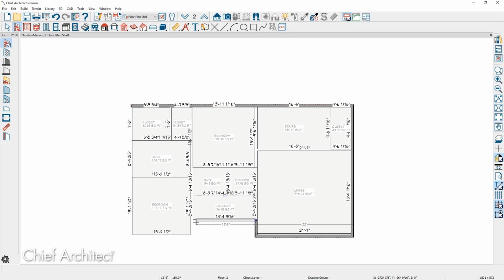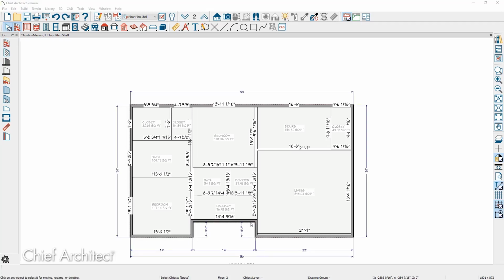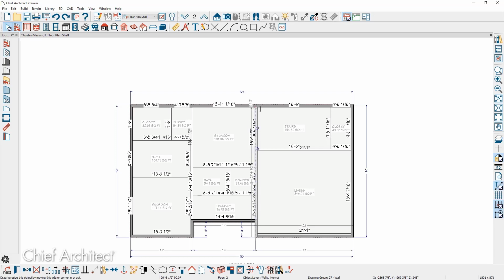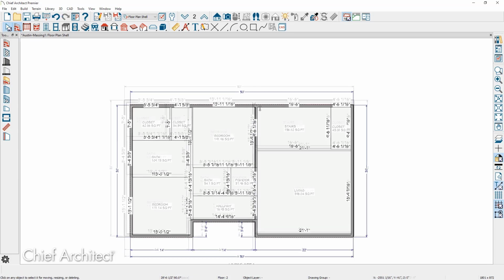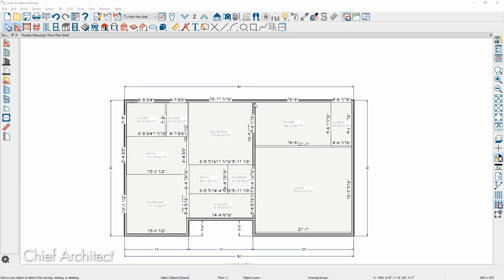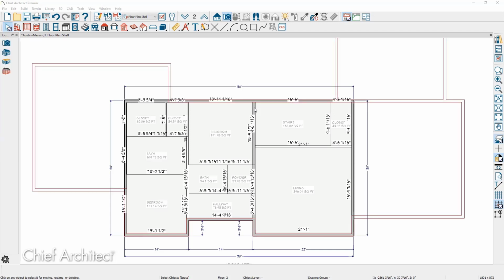On this second floor, I will add one interior wall. The reason is that I want to use the room's ceiling height to make adjustments for the roof and wall heights. Since I previously built the second floor before there were walls, you might need to align the walls from the first floor. To assist with that alignment, you can use the reference display feature to show the walls below. Press F9 on your keyboard and it will superimpose those walls. Then you can position the walls on this floor accordingly.